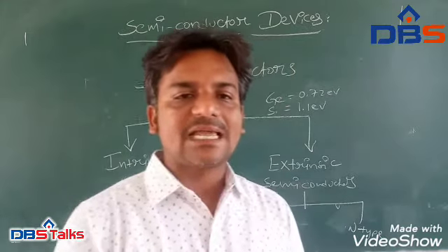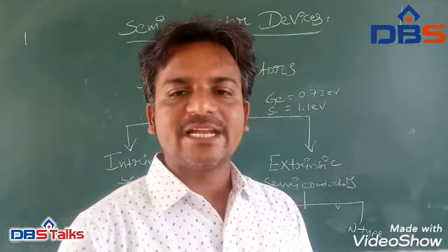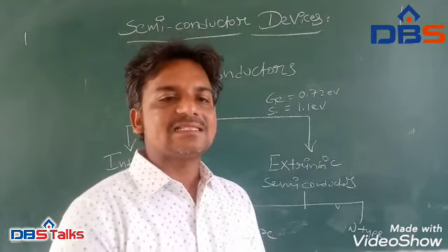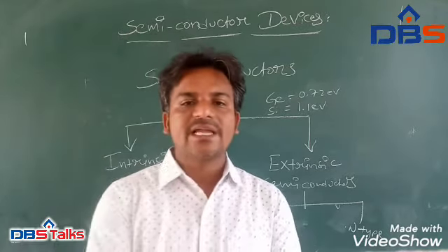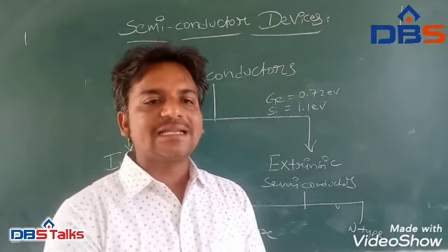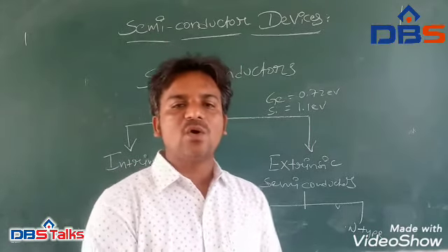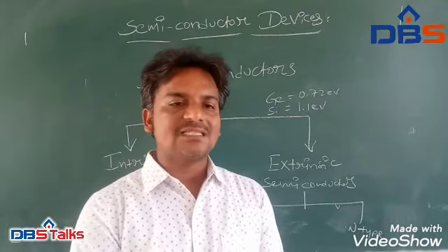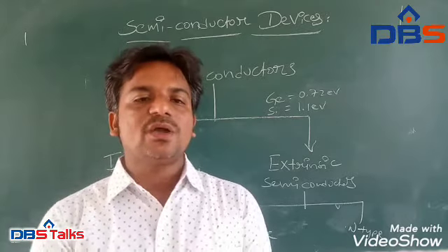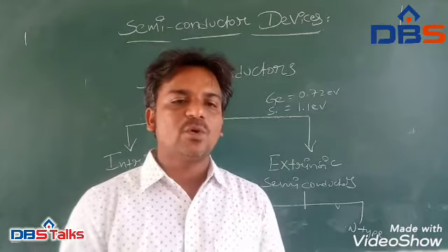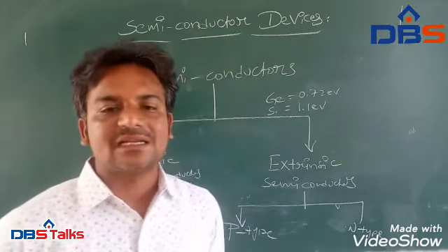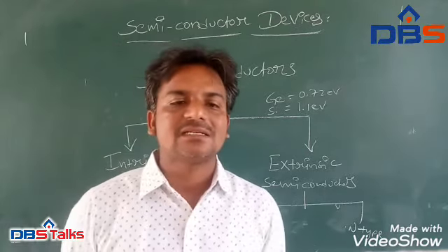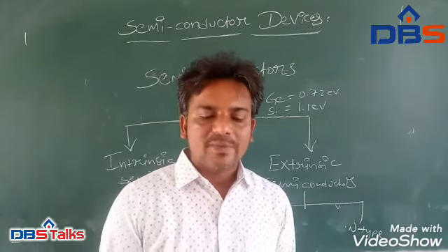An extrinsic semiconductor is one that has been doped, that is, into which a doping agent has been introduced, giving it different electrical properties than the intrinsic pure semiconductor. So doping involves adding dopant atoms to an intrinsic semiconductor, which changes the electron and hole carrier concentrations of the semiconductor at thermal equilibrium. The dopant carrier concentrations in an extrinsic semiconductor classify it as either an N-type or P-type semiconductor. The electrical properties of extrinsic semiconductors make them essential components of many electronic devices.